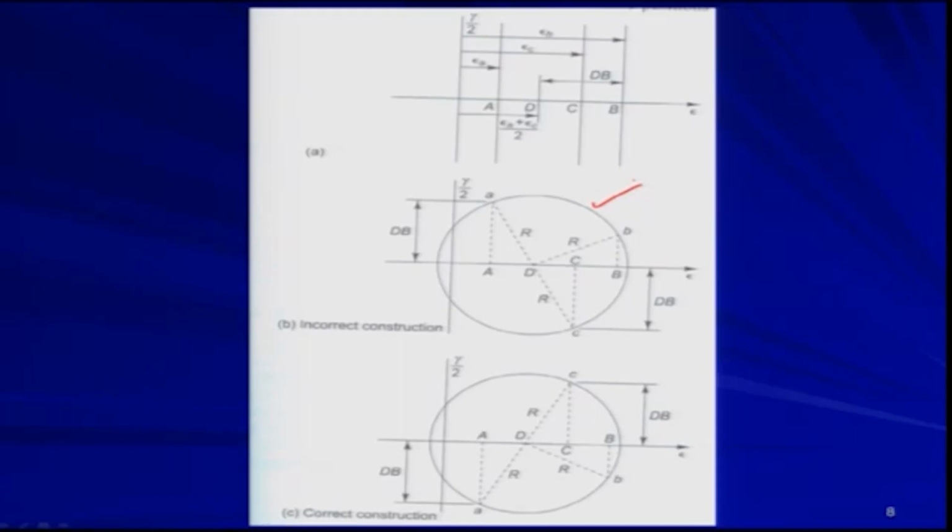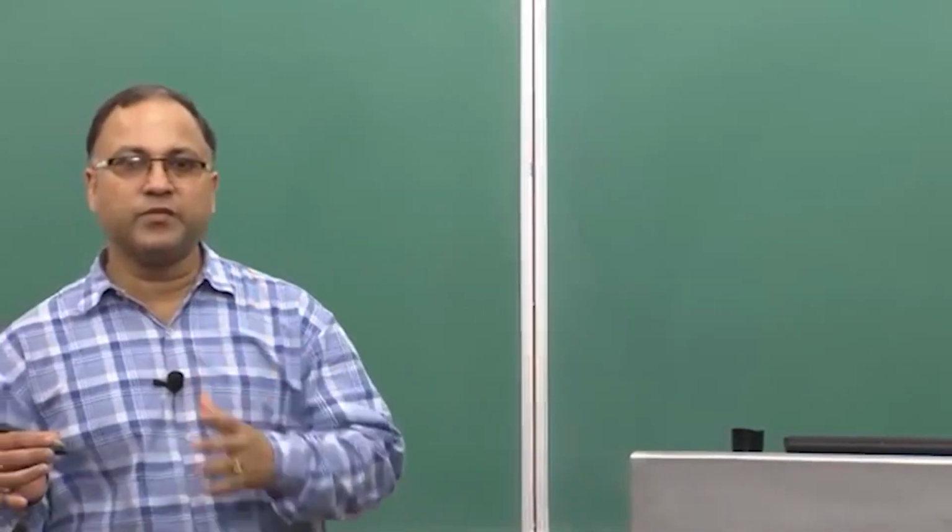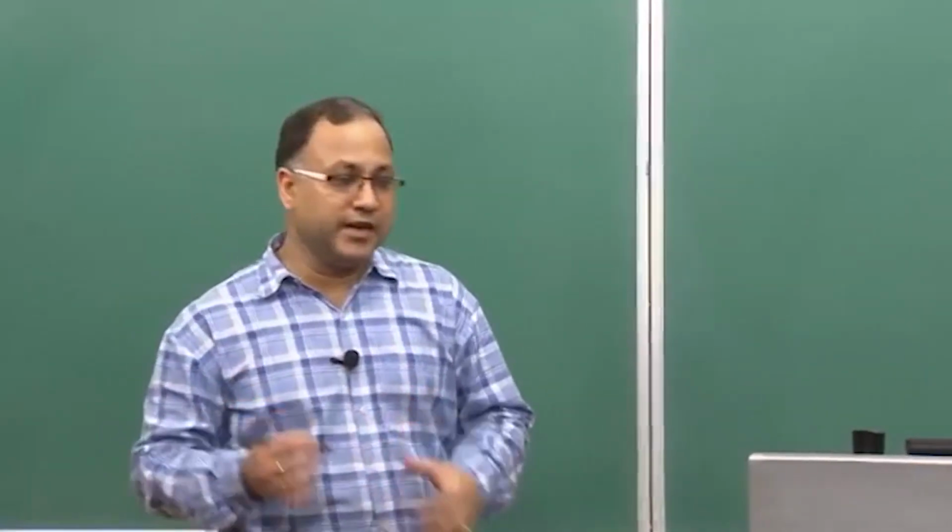And we have 3 points, point A, C and B. These 3 points are giving me the normal strain measurements for the 45° strain rosette. Those normal strains come from the strain gauge readings.